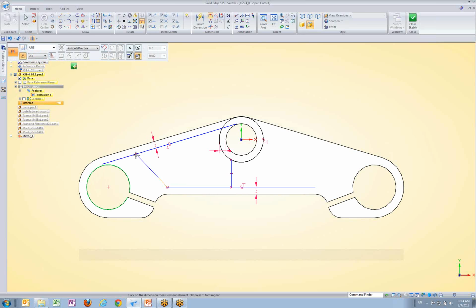So let's pick up on that center there and that intersection point. Drop a distance between and make that 25. I'm using this radial menu a lot. It's a nice way to prevent you from having to reach up to the toolbar all the time. Saves you a bit of wrist strain. Let's make that 125 degrees in there. And last, I'll grab a distance between and offset this 5mm.